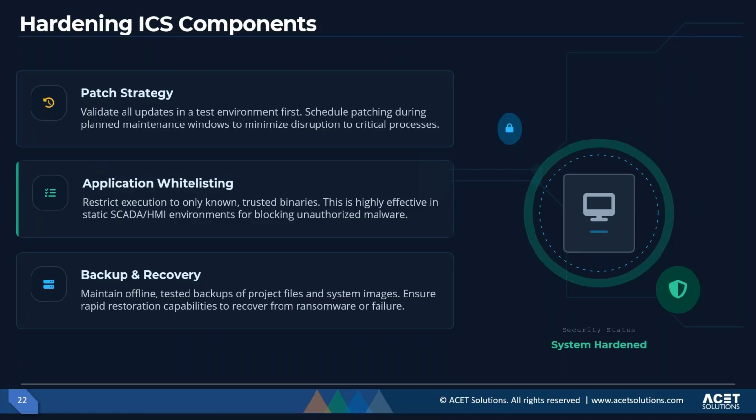Backup and recovery capabilities are the last line of defense. Every critical component, PLC, HMI, SCADA server, historian, switches, firewalls, and engineering project files, must have scheduled and verified backups. And these backups must be stored in both online and offline locations.